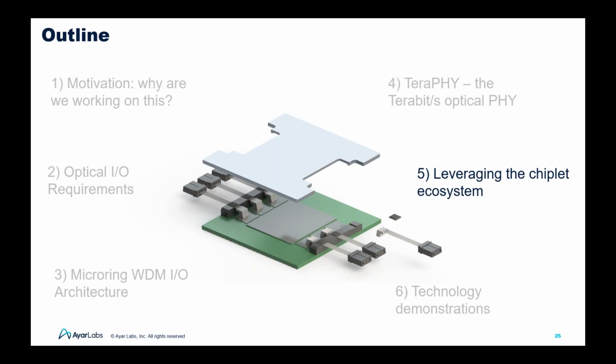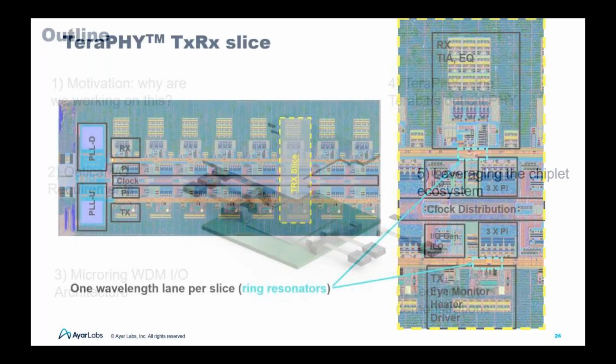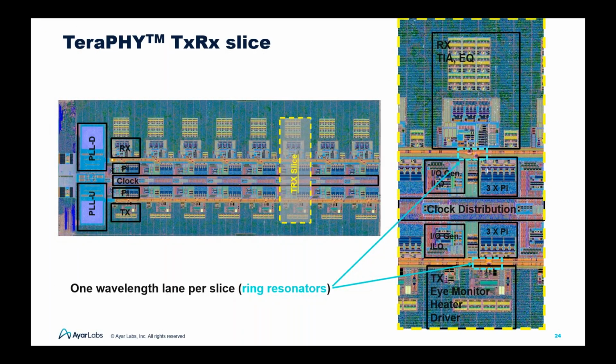Yes. So in the previous picture, does that mean you have like 80 different lasers connected to one die? Actually, we have 10 fiber cables coming in, and each fiber has 8 lambda laser. Yes, 80. I don't want to say 80 different, but there are 80 lasers, categorized in 8 wavelengths. Basically, we have 10 lambda 1s, 10 lambda 2s, all the way to 10 lambda 8s.